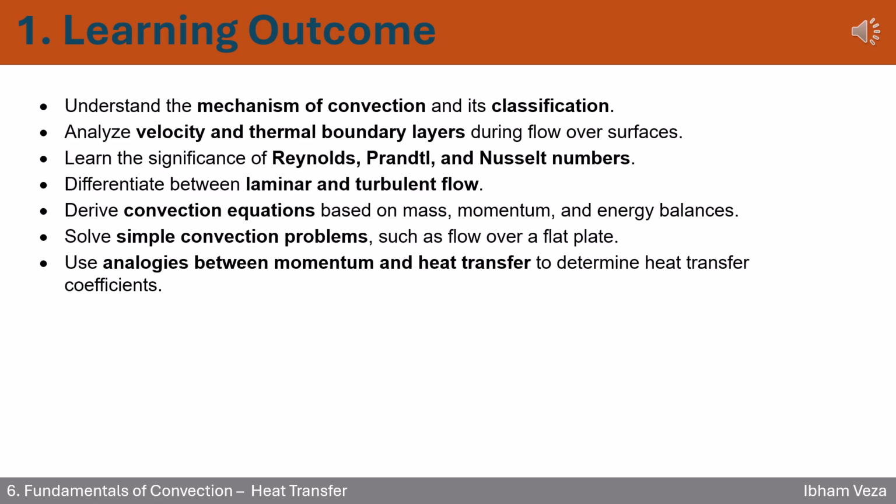First, you'll understand the mechanism of convection and how to classify it. You'll see the importance of velocity and thermal boundary layers and master critical dimensionless numbers like Reynolds, Prandtl, and Nusselt. You'll be able to differentiate laminar from turbulent flow, derive equations from the basic principles of mass, momentum, and energy, and solve simple practical problems like flat plate convection.